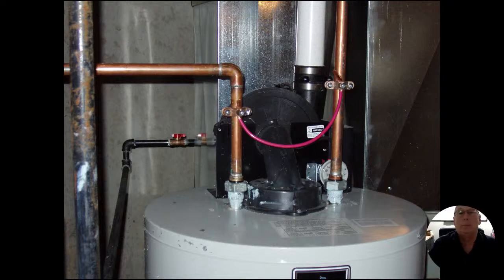I think this is a great practice as well. I'm seeing it more and more in communities, which I'm pretty happy with. So they'll jump over or bond both the hot and cold water side of the water heater. Usually I'm seeing that same wire will continue on and go to that gas pipe that's to the left. So they'll put all 3 of these together and make sure they're all the same potential. And again, if somebody has to switch out this water heater, once you remove that water heater, you break all the bonds of those different items.